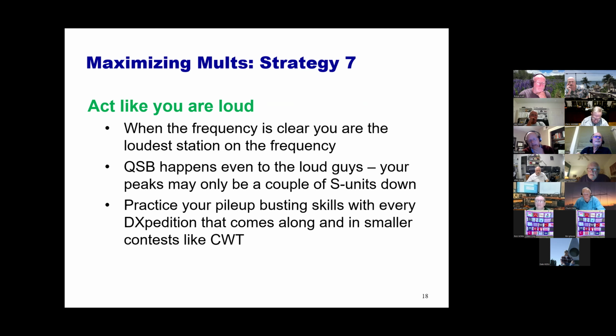And another thing that I probably should have mentioned is be sure not to call zero beat. If you call zero beat and there's a pileup going on with two or three other guys that are calling zero beat, what the operator at the other end hears is, I can't hear any dits or dots. But if you call a little bit lower, he's going to copy you through that carrier of two or three guys that are calling on his frequency.